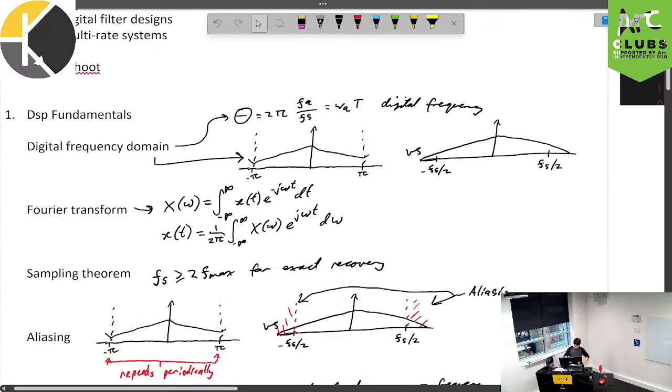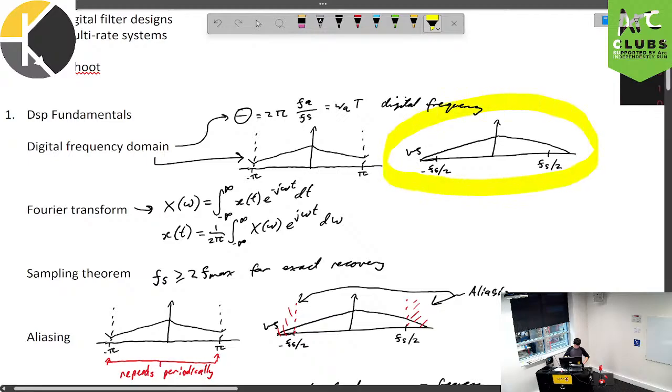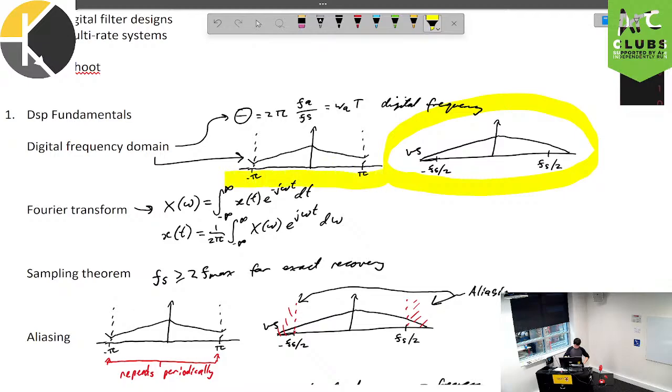And the main things that we want to take note of are just going to be concerning how we convert from our standard Fourier given frequency domain to our digital frequency domain. Okay? So digital frequency is essentially just scaling the entire thing down by a factor of your sampling frequency, multiplying by 2 pi to put it in radians, and then making it periodic. Okay? So you'll note this little thing is periodic after the ends of pi. The little end bits get snipped off.